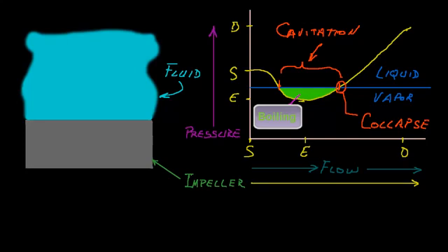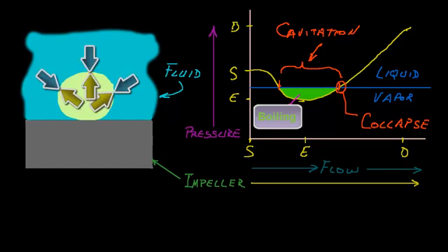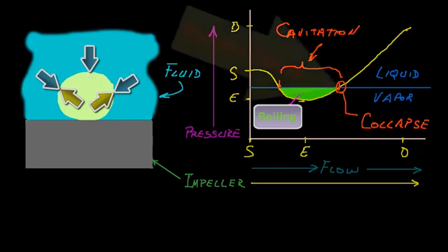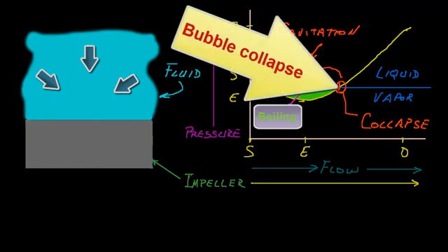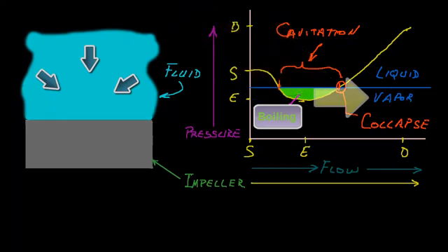Returning now to our earlier illustration, similar to the collapsing balloon that we just saw, as the pressure of the fluid increases during the pumping cycle, at some point the vapor pressure inside the gas bubble is unable to support the external fluid pressure of the surrounding liquid. At that point, the gas bubble collapses or implodes under the pressure, or in other words, the gas bubble vapor quickly changes phase back to a liquid state.